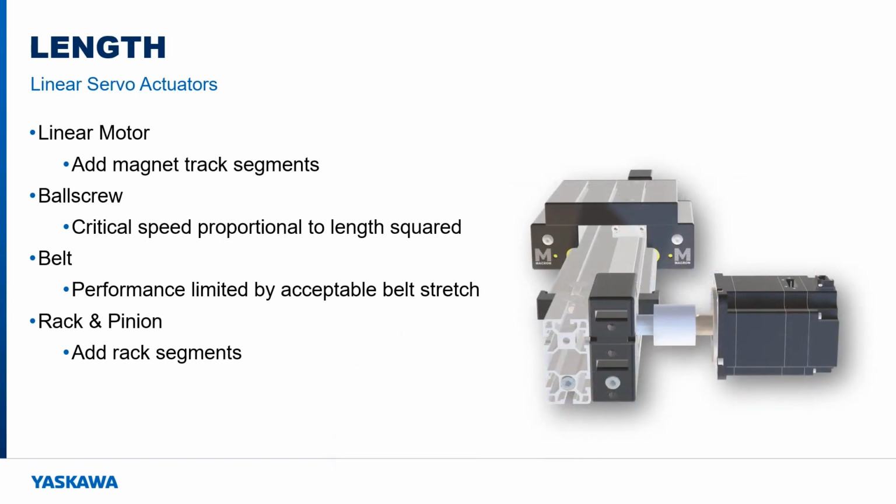Belt drive designs are easily lengthened with minimal increase in cost. However, the effect of belt stretch becomes proportionally worse, resulting in reduced accuracy and repeatability. And like the ball screw, with increased length comes decreased stiffness and the problem of lower resonant frequencies.